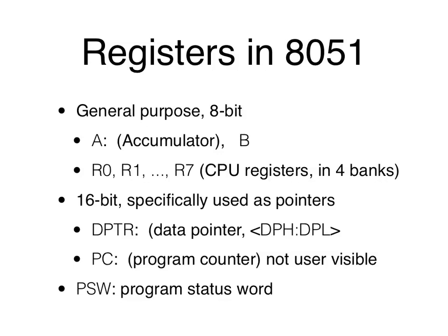That's what a program counter is. There's something called PSW, or program status word, and that includes a number of bits that indicate the status, whether or not you have an overflow, or you have a carry, something wrong happened. Okay, so that's what PSW is, and we'll go over some of the details in a little bit.